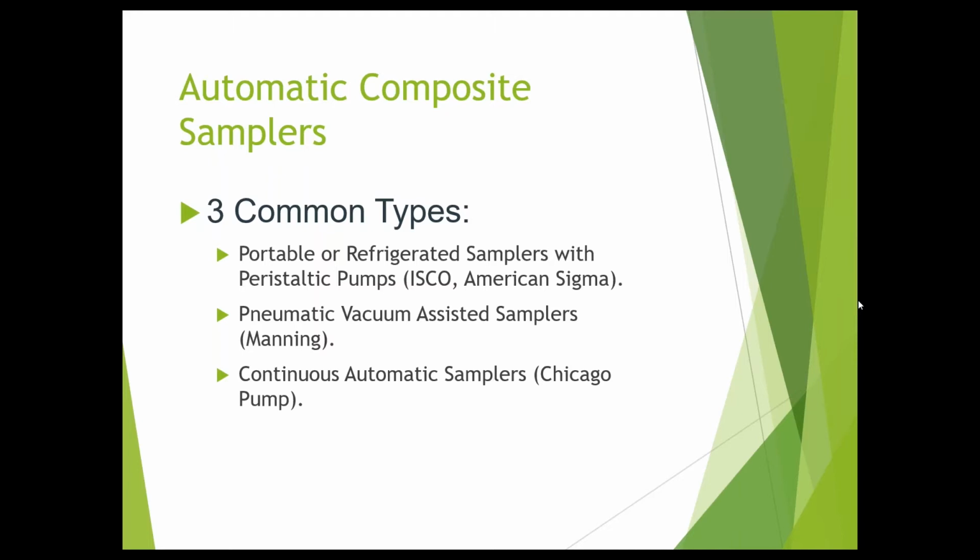If we are trying to enforce a permit, that's different. If you're enforcing a permit, then you should follow the permit. So in that case, I would say flow proportional because you're enforcing a permit, and you can't readily say that this is a perfect one-to-one match. Again, it depends on the type of plant. If you are at a traditional mechanical plant where you have steady effluent and it says flow proportional, there are studies, and I just completed the draft of one, that say if you sample at 15-minute intervals, that's the gold standard. At a mechanical plant, the results are almost identical to what you would get if you were to do flow proportional sampling.